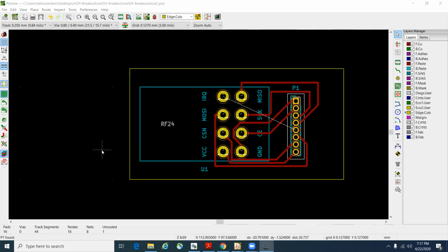In this lecture we will learn about wiring between pins of the two footprints, and this wiring is basically called routing. For that you need to find a good path for connecting the wires as they travel through the PCB. You have to be very careful to avoid any crossing between two traces when routing between the footprints.